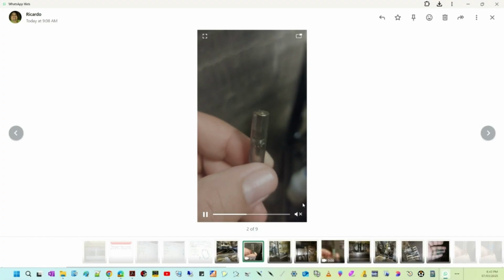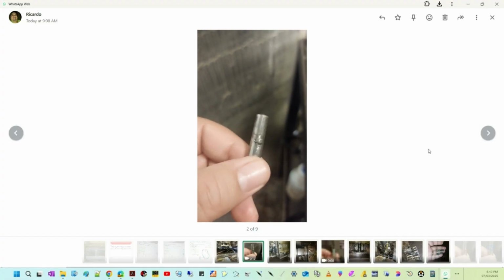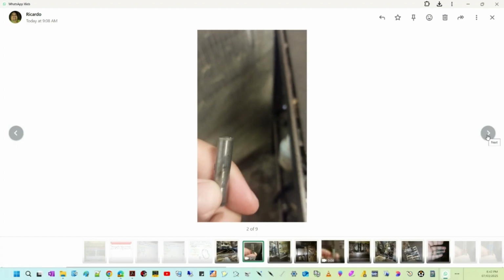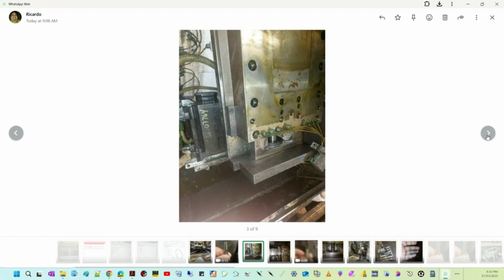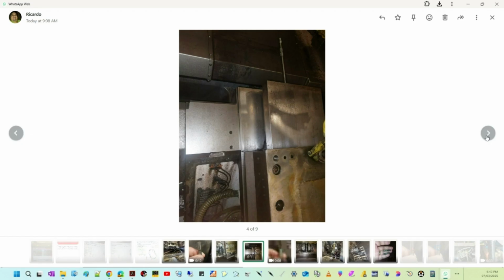They're small, but their job is critical. They ensure the turret is perfectly aligned, perpendicular to the X-axis cross-slide. If they're damaged, alignment goes out the window. Okay, so damaged pins. What else? Even more telling, they found a lot of shavings near the bearings. Metal shavings are never a good sign. It points to friction, wear, something grinding itself apart.